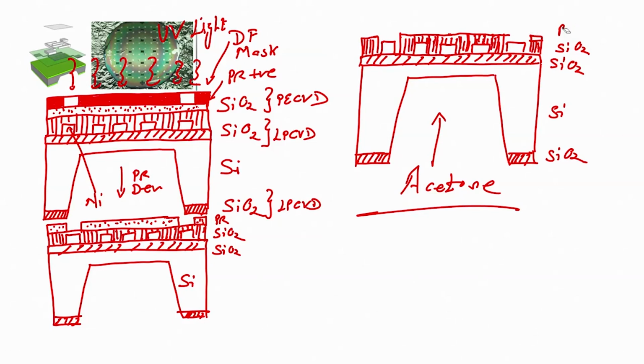Photoresist will be stripped off. So, now what you have is silicon dioxide protecting your micro heater, right, except in the contact area. Now if we apply power or voltage here, because of the resistance of the heater, current will flow and the heater will heat up.